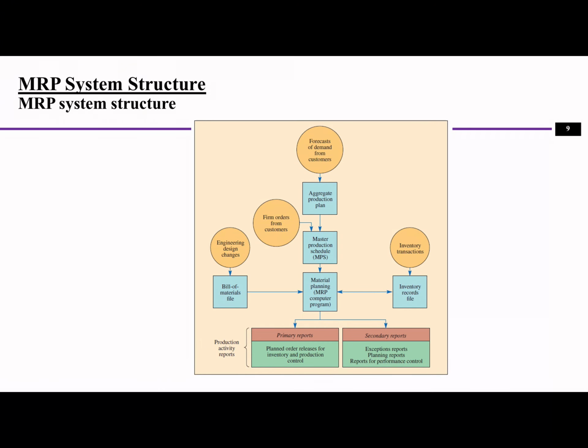Alright, so this graph mainly shows how the MRP system works in this whole production system scheduling and also supplies. This is a master production schedule. Based on the master production schedule, we get a forecast or the demand from the MPS. Then the MRP will get information of the demand. Then based on the demand and also based on the bill of materials, we can deploy or start to explode the MRP to see what products or what parts will be required and at what time.